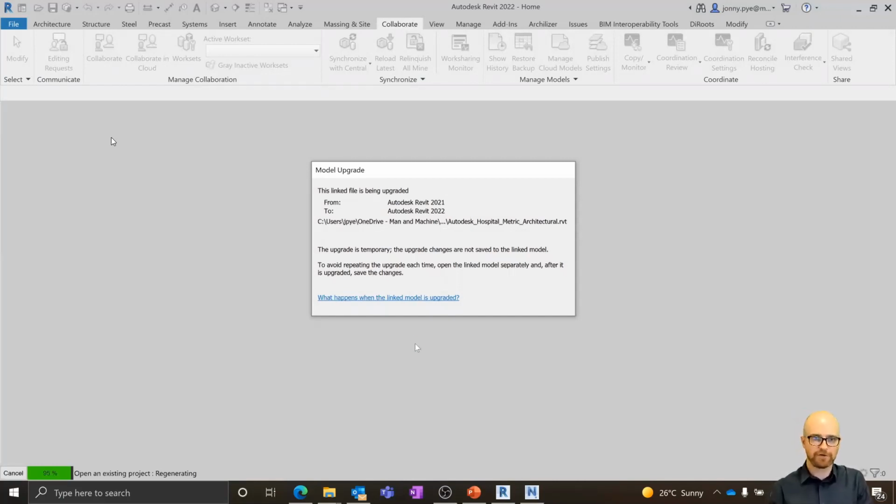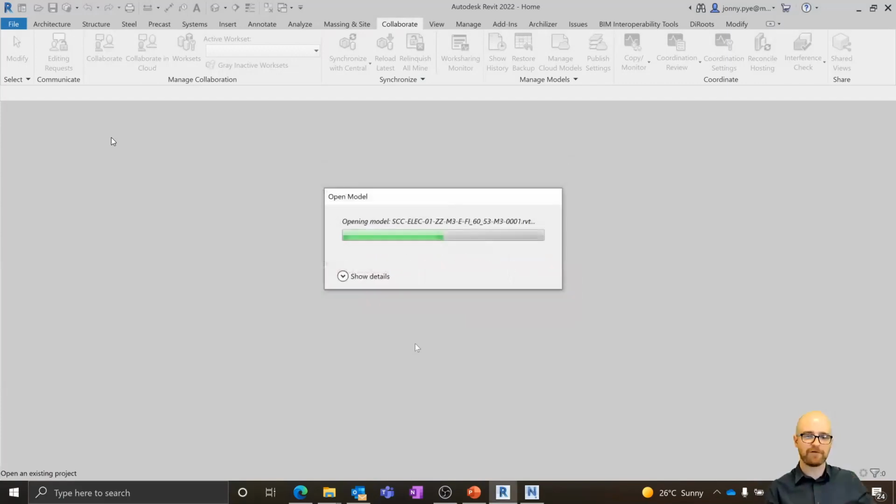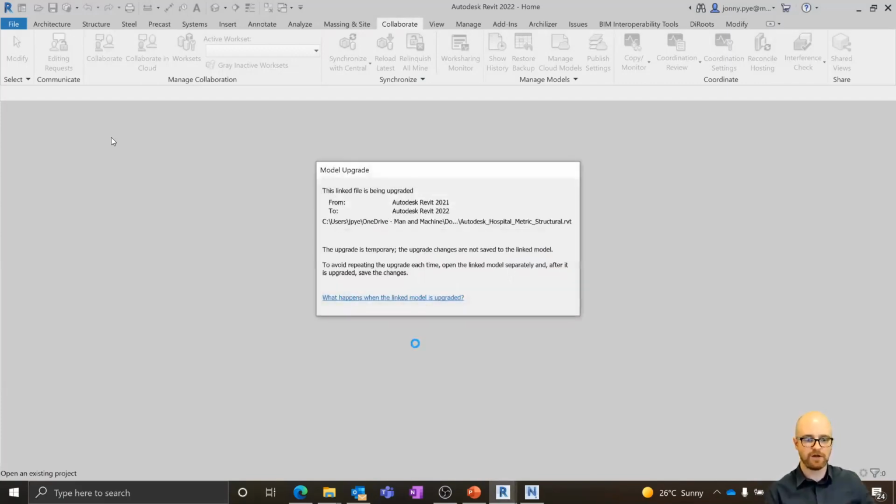So that will be suffixed with a little BIM 360, I think it is at the moment, but essentially there's a workflow from Navisworks through to Autodesk Docs if you wanted a bit of a review, and then into Revit if you needed it. So if you're doing maybe clash detection that's going to pick up on things that aren't necessarily hard clashes, then Navisworks is going to be your kind of go-to.